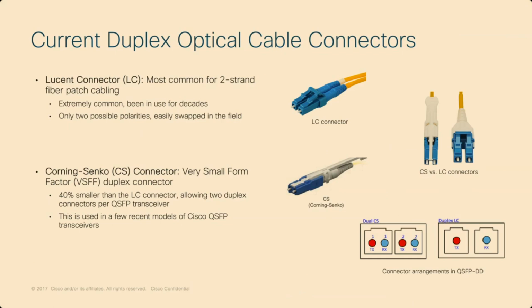One of the nice things about this connector is you can always swap the polarity of the cables. So you can see one of these cables on the top here has a little white sleeve around it, and the other one has a yellow sleeve. You can actually swap the position of those 2 fibers on that connector if you need to change the polarity of the connection.